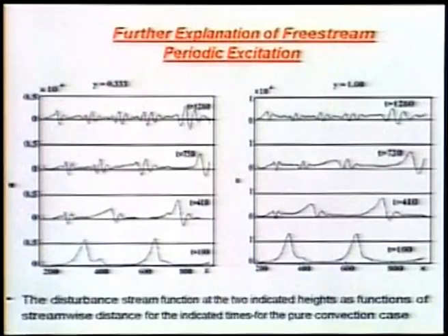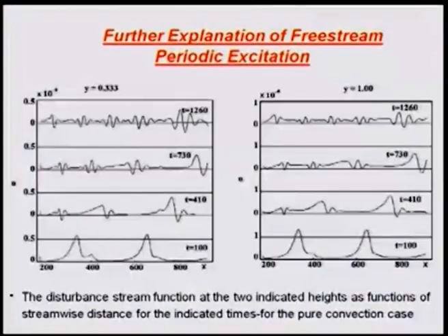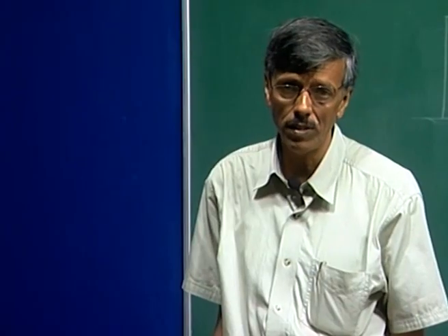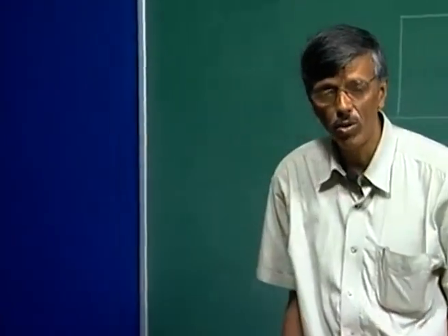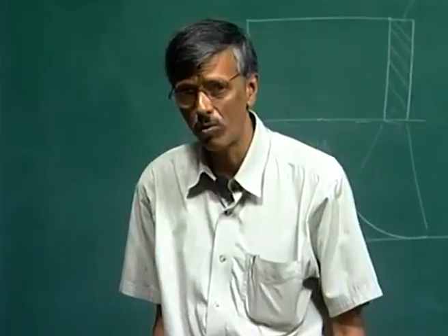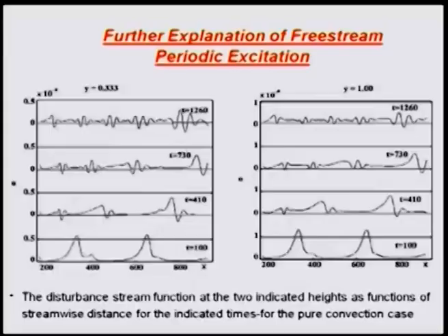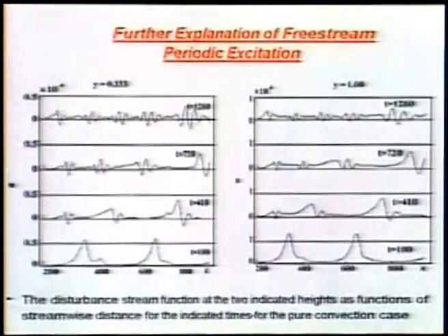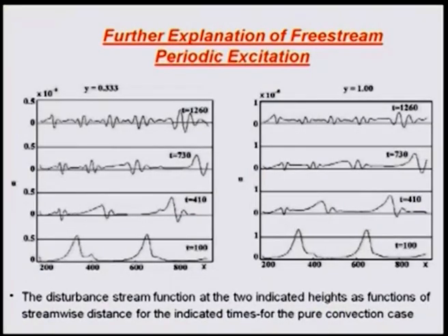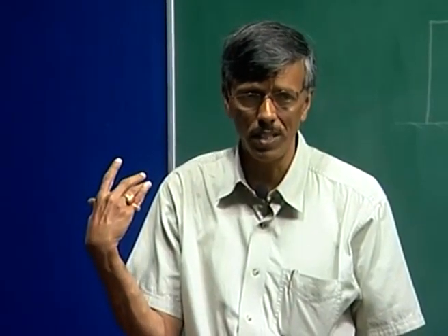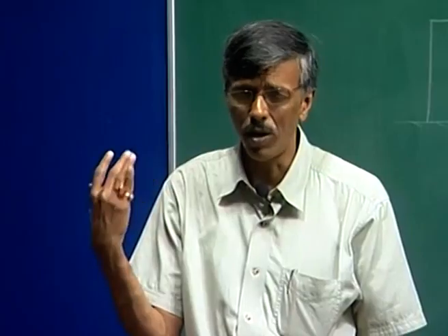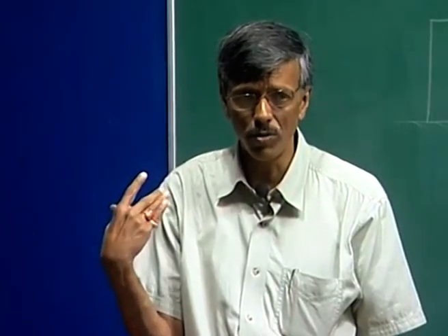Okay. So, that is what you are seeing. In addition, of course, you do also get to see some kind of downstream propagating modes, right. Those downstream propagating modes go at what speed? It depends on what we have seen before, on the local Re delta star, and we have seen the TS waves go at something like, well, in this case, of course, there won't be any TS wave going, because c equal to U infinity, you will only have those damped modes.